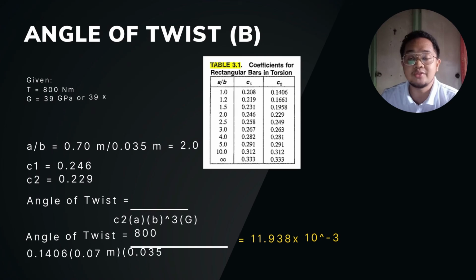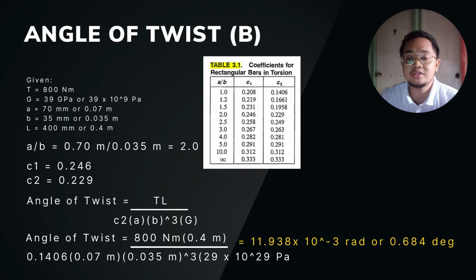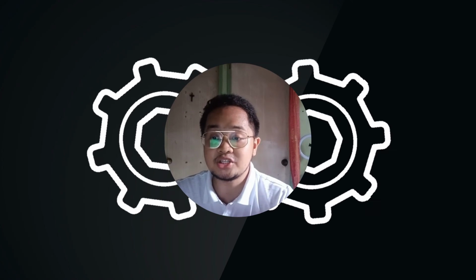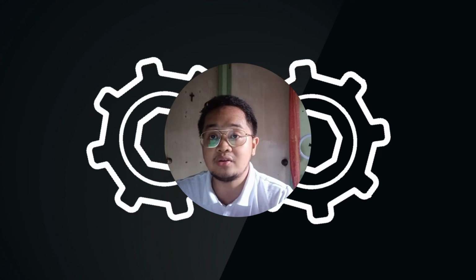For the angle of twist of end B for figure B, we have C1 equals 0.246 and C2 equals 0.229. Substituting the values to our formula, we get 11.938 times 10 to the negative 3 rad, or 0.684 degrees. Therefore, for the angle of twist of end B for figure B, it is 0.684 degrees. That is how we calculate the maximum shearing stress and the angle of twist of rectangular bars in torsion.